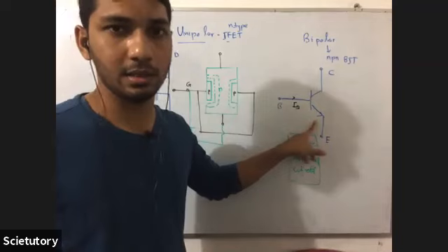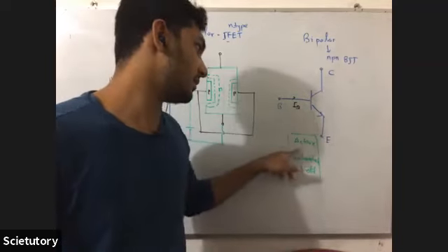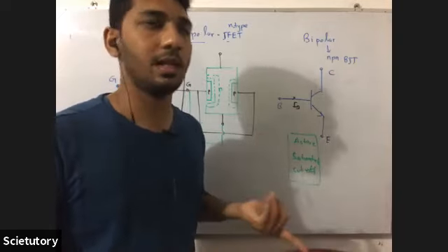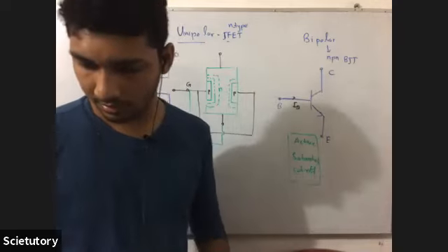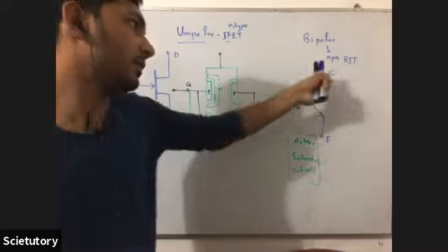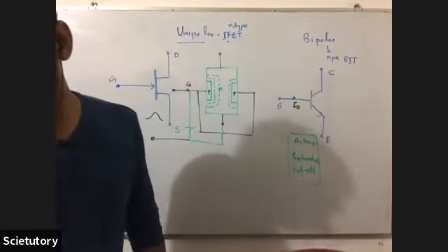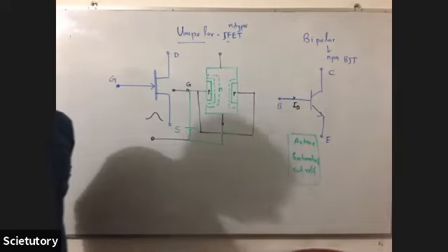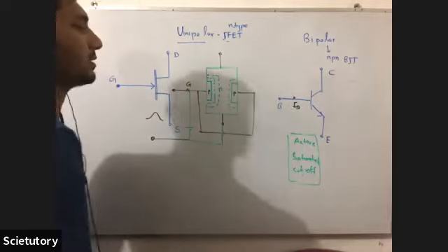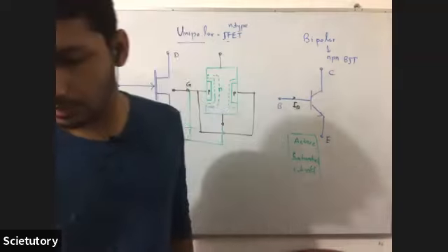Base emitter voltage determines whether that transistor is functioning in active state or saturated or cutoff, so it actually affects the current. Okay. So if it is reverse biased, whatever the input, the collector current is what? 0. In JFET, the magnitude of the current flowing through the channel depends on the gate source voltage. Yeah, that is correct. Okay, gate source voltage affects the functioning.